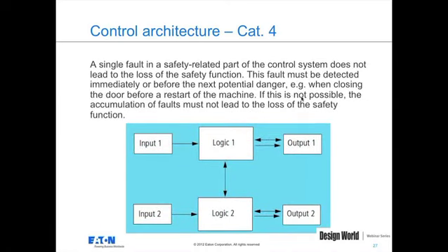And then obviously building upon that is Category 4. Again, any single fault cannot lead to the loss of the safety function, and the addition is that it must be detected before the next potential danger.